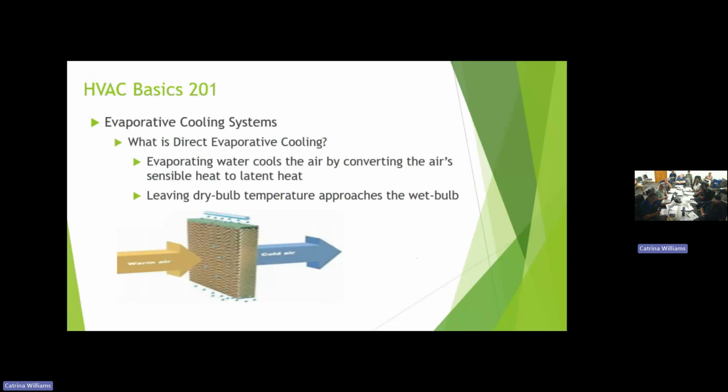Just because of the working conditions. Yeah. They just had to be dead on their feet by the end of the day. So that's what evap cooling can do. But again, we don't return it. It's one time through and we're out. But it's inexpensive too. You don't have any refrigeration system to worry about. So just pumping the air through. The only thing you have to do is replace the evaporative media pad.